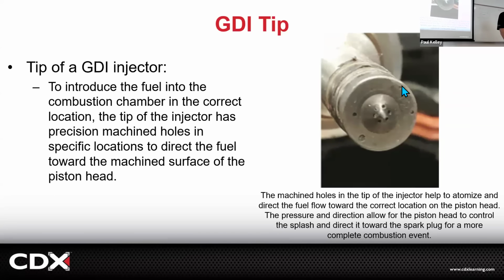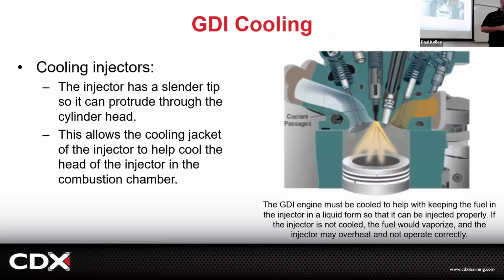Cool. So there's a little bit more to these. Running the top tier fuel is going to be good. Some people would even go for adding a fuel injector cleaner periodically on a maintenance. Not really a bad idea. But I don't have all the evidence and collection on that. You'd have to test thousands of cars to see if that's helping, but there is at least some logic behind adding some sort of cleaner. Cool. And then overall, these injectors work a little different because they're going to get hot. And so we have coolant passages to carry the heat away. It's the way it's going to work. These newer engines make a lot more heat. They're running a lot more efficient.